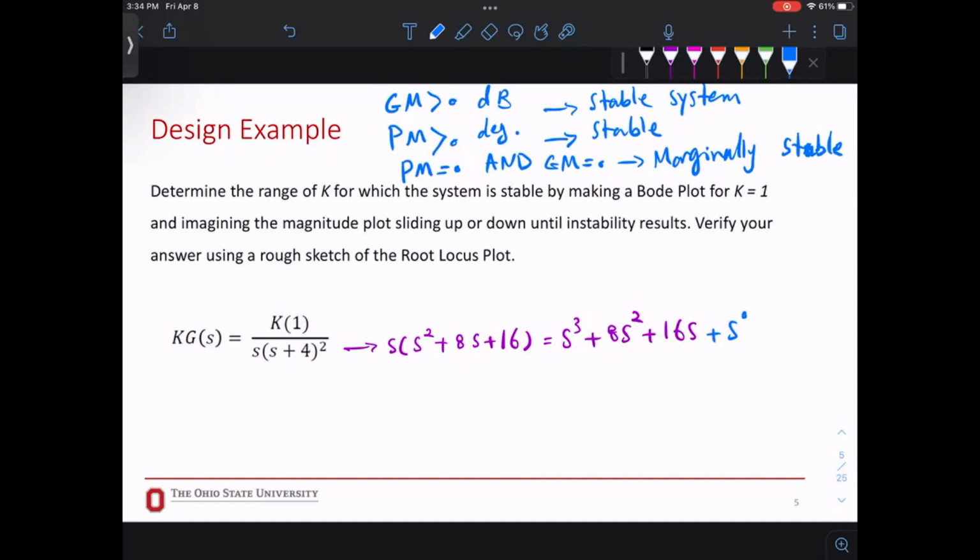It means that if you draw the root locus, some of the branches are going to be on the right side. So I predicted this. You give me a system, I'll tell you. If you have all the coefficients, it doesn't mean the system is stable or not, and you can't draw any conclusion. But if one of the coefficients is missing, one of the powers of S, it is definitely unstable for some value of K, meaning some part of the root locus goes on the right-hand side, right?